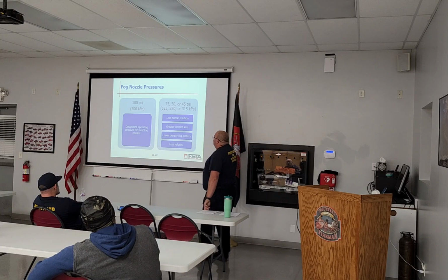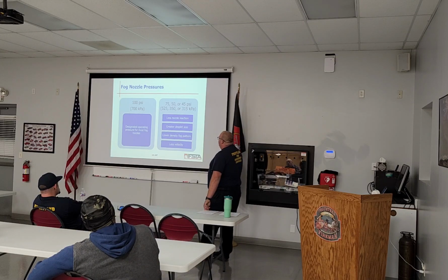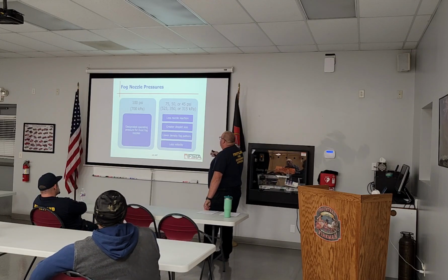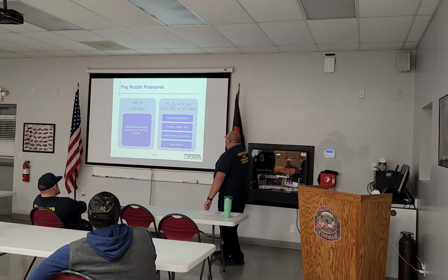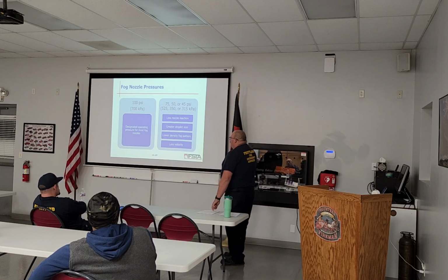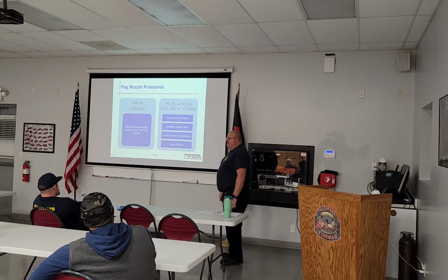So fog nozzle pressures, you got 100 PSI, the designated operating pressure for most fog nozzles. And then on your solid streams, you got 75, 50, or 45 PSI. Less nozzle reaction, greater droplet size, lower density fog pattern, and less velocity.